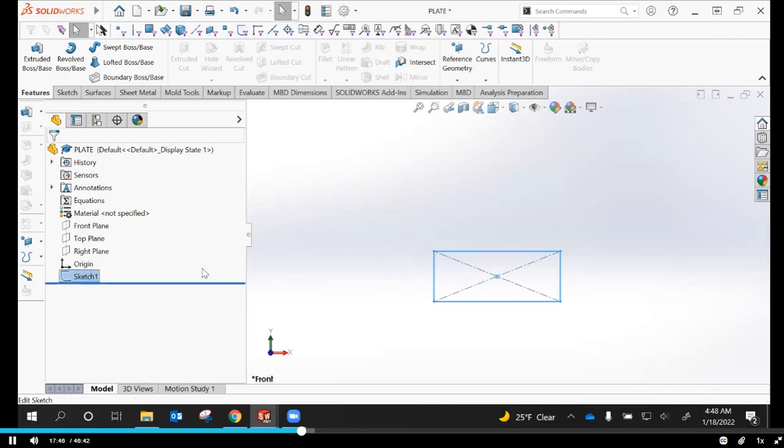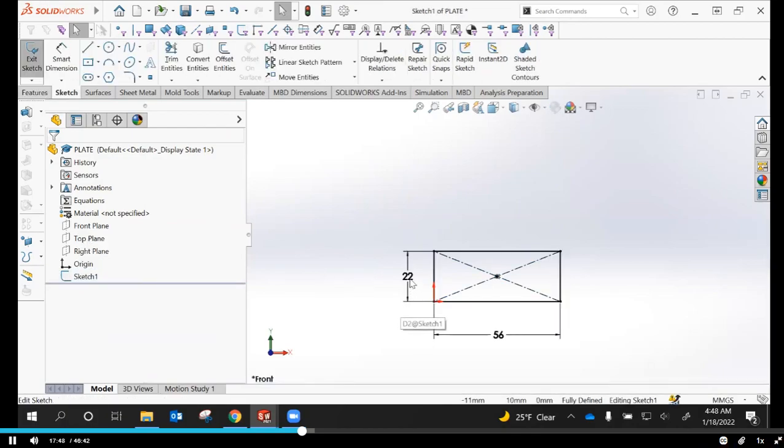What does it look like if it is not fully defined? If I get rid of that dimension, now there's a little bitty parenthesis right here. It looks like a TIE fighter from Star Wars. It looks like this, like that with a little dash in the middle and then another parenthesis.